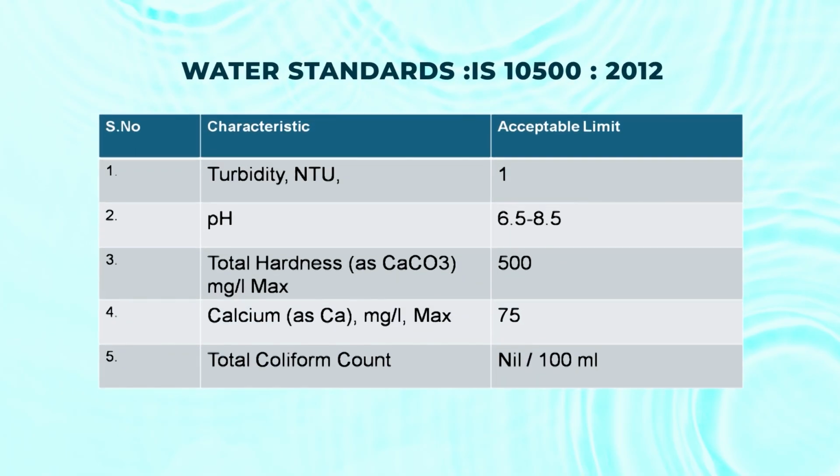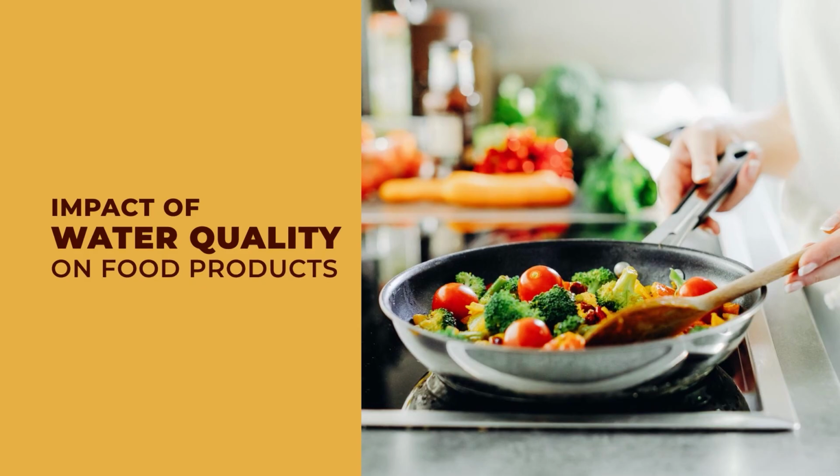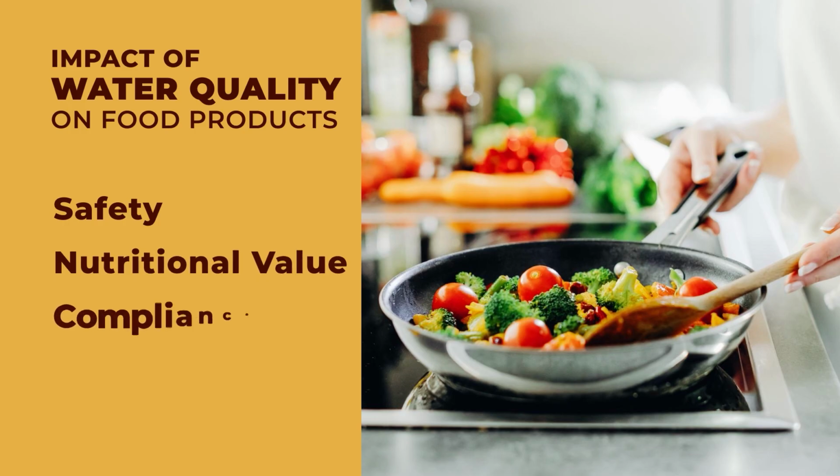So these are the standards for IS 10500. pH should be 6.5 to 8.5. Total hardness should be 500. Calcium should be 75. Total coliform count should be nil per 100 ml. This has an effect particularly on flavor, taste, texture, and shelf life. Poor water quality will give a poor product. It also has an impact on safety, nutritional value, and compliance.